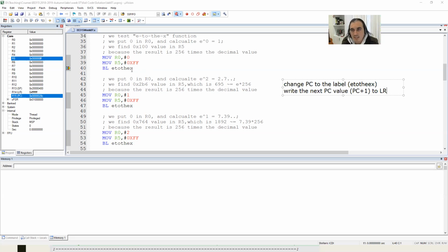Since this is the code that we are executing right now, it must be written in the PC and its value, which means PC is at this address in the instruction memory. I'm writing the value from here. Any questions about this?